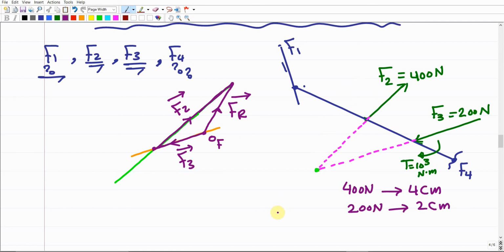And this is what we're gonna do. So your objective is just to, starting from this point, draw a line that is parallel to the FR that you got. So that's why this polygon should be very close to this drawing, and everything is drawn to scale. So you're gonna draw a line that is parallel to this FR going in this direction. This definitely gonna give us the FR that we just calculated. This is the FR vector, and now this FR is fully defined.